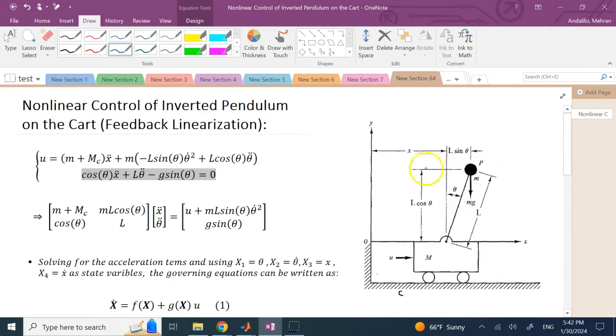So last time we did a linear control, so we linearized the system. We assume that this theta is less than or equal to 6 degrees. It's a small angle, and so we can approximate cosine theta by 1, sine theta by theta, and anywhere you see a term that has all of these several terms, you can approximate it by 0. And that makes our equations extremely simple.